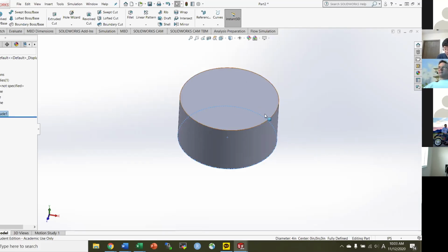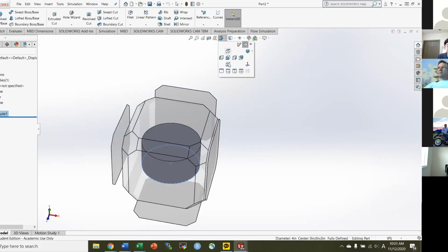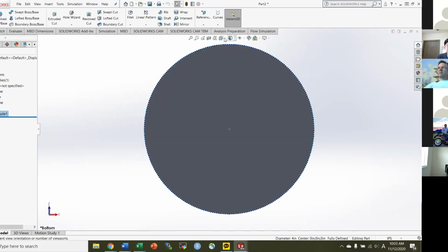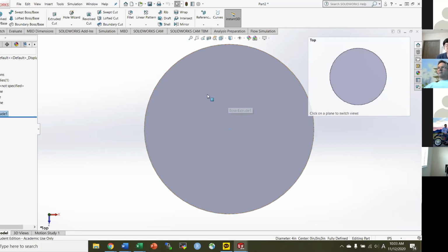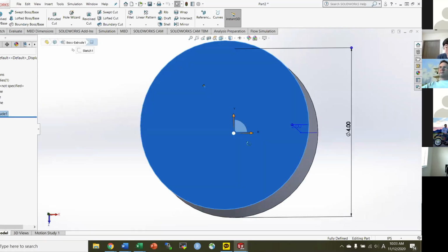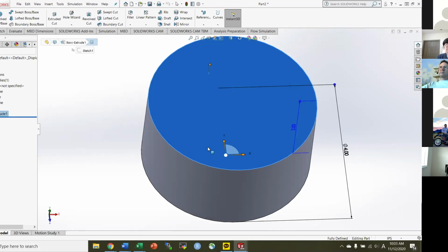And I'm going to now make a hole in the middle and then another hole in the edge, to make it into the probe part. So I'll go to the bottom. Actually, I'll go to the top side of it. If you want to cut it, there are different options, but a simpler way, I guess, is to click on the top surface. So if you rotate it, you'll see that only the top of the cylinder is selected. If you click on the side, only the side will be selected. And right now I want to cut into the top part.